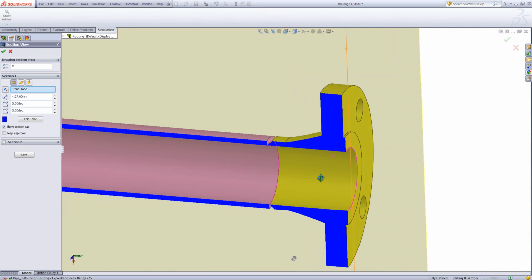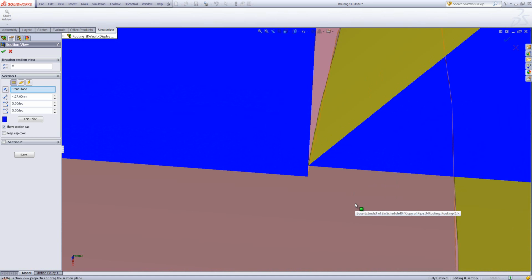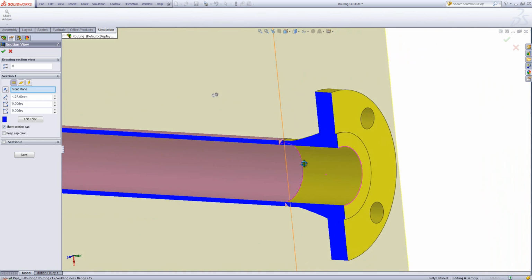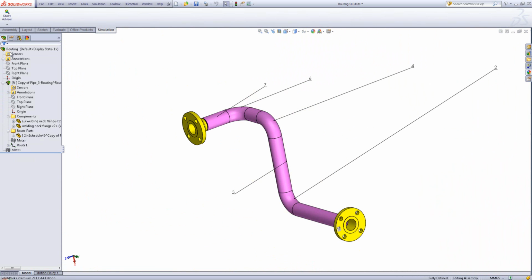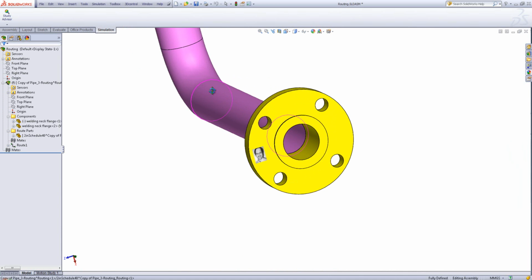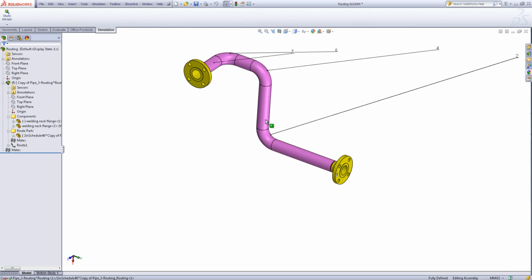So we're going to have to deal with that pretty specially, because we've just got essentially an edge-to-edge contact there. We're not too happy about the way that bond is being executed, so we'll have to be very careful when we come to that in the analysis. Because we have a very long and slender geometry, with a thin wall thickness and large dimensions in the other two directions, I'm going to take a slightly different approach to just using a standard three-dimensional mesh.